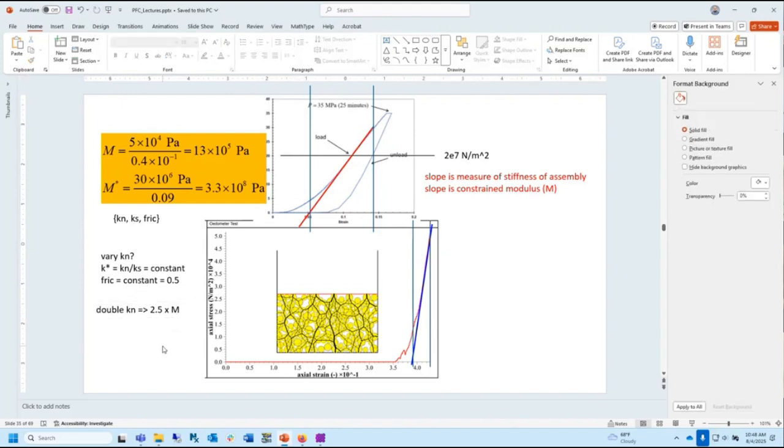Makes sense? So think about this system now. From what we've seen, these KNs are springs in here. What we're doing now is measuring the overall stiffness of all those springs getting pushed. And just think, if I replaced those springs, kept them all in the same locations, but put in springs that were twice as stiff, the overall result is probably going to be a curve that's about twice as stiff. That's kind of what we saw here, right?